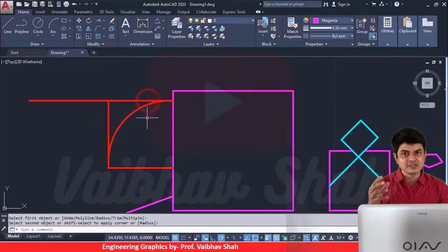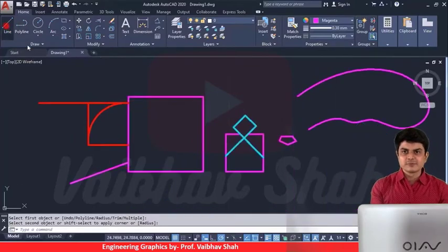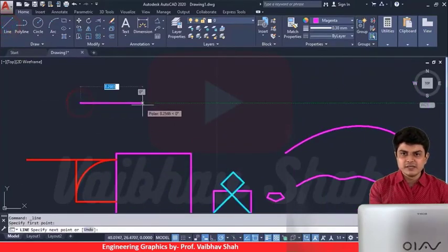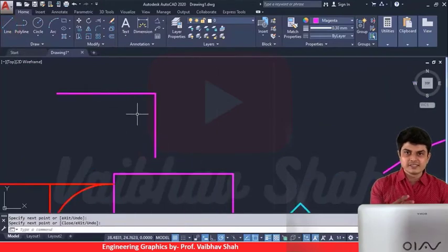You can have this arc generated. So this is how you can generate the circular arc or corner by the intersection of two lines. It is very easy, right? So now you can see the fillet. Now let us suppose that after the fillet, we don't need those lines also. We just need the corner, not the line, right?